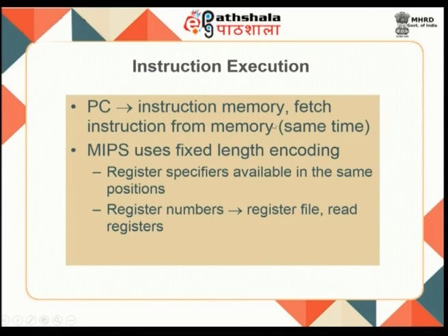So, the first part of your instruction execution is your instruction fetch, that happens uniformly, and then you go in for the decode of the instruction, where it is not only the decoding that happens, you also read the register contents from the register file, because it uses fixed length encoding.